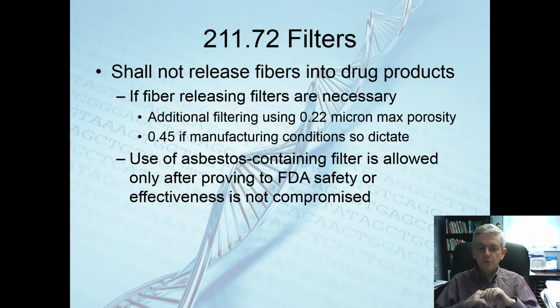21172 talks about filters. Filters should not be releasing fibers into your drug products. If fiber releasing filters are used, there's some specific requirements here about that. Use of asbestos containing filter is allowed only if you have a letter from God, and that's tough. Let me say that there's a lot of safety and effectiveness things that have to be considered here. I would highly say don't use asbestos containing filters unless you absolutely have to.